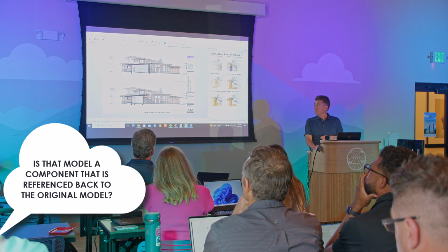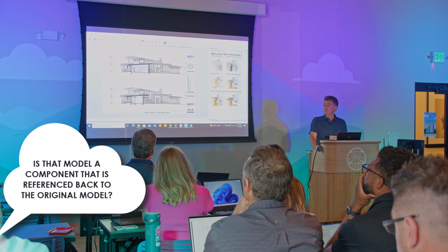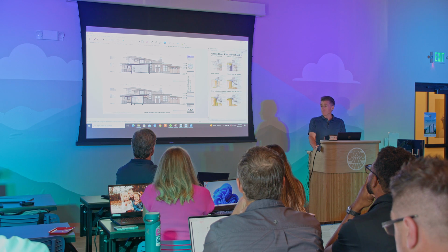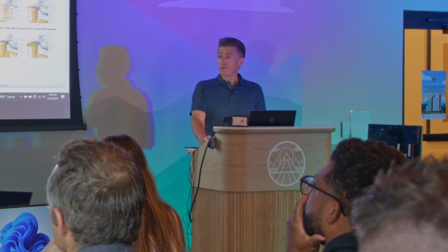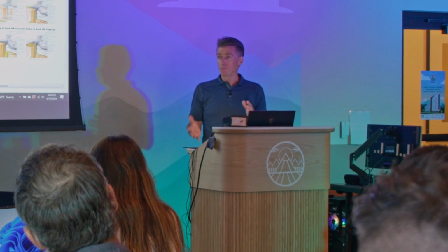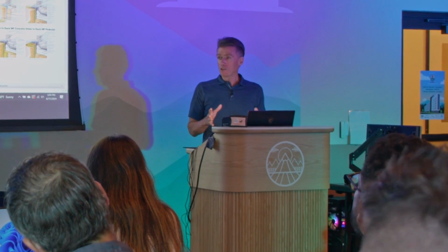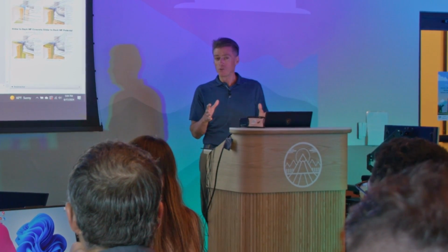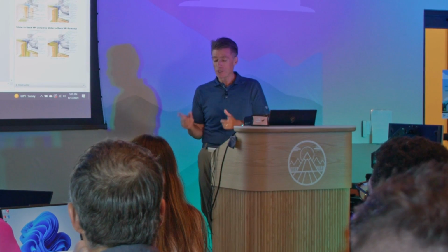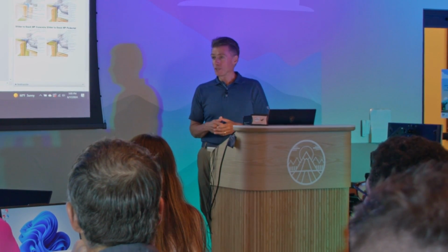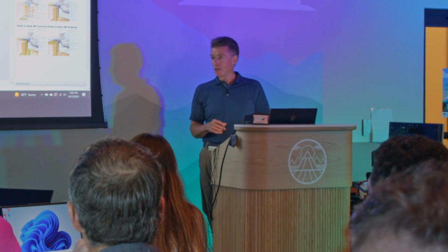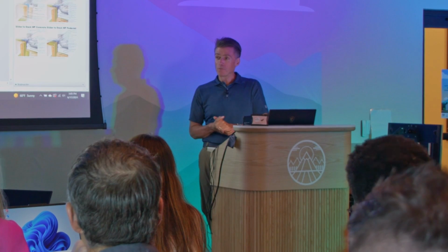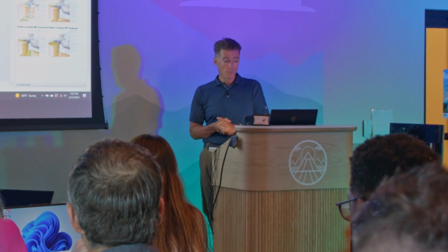That model, is that a component that is referenced back to the original model? Yeah, so if there's a change, I just update. That component will update. We don't have multiple models that we're trying to remember. No, you don't have to do that. So you do have multiple models. So if you make a big change, and it depends, some changes you don't have to pick up because they're so minor, but if you make a big change, you then go open up your SketchUp section model, and you update the reference, and that's it. Then you save it, and then in here, you update the reference also.